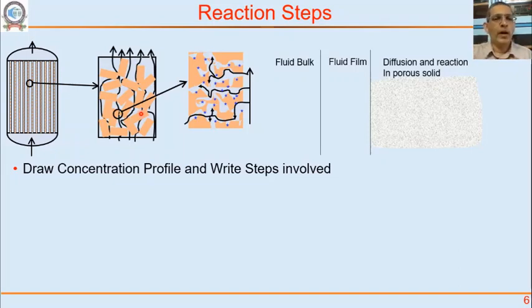And if you look at one of this catalyst pellet closer, you might find that this is a pellet and this catalyst has pores inside, and inside these pores there are active sites. So these blue stars are these active sites. So these active sites are distributed in this catalyst pore, and then when the reactant flows, the reactant goes through this catalyst pore and it reacts at these active sites. Okay, that's how these reactions occur, and whatever product is formed from that active site, it again goes back and desorbs and then goes along with the gas phase.